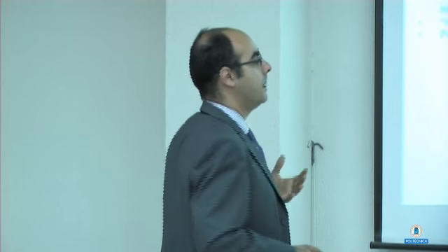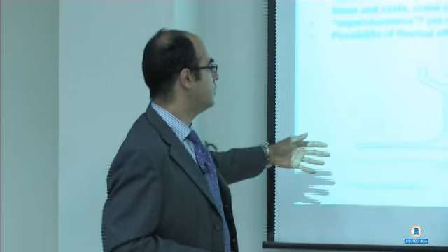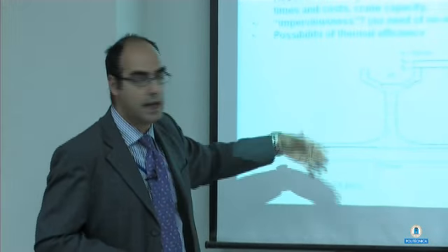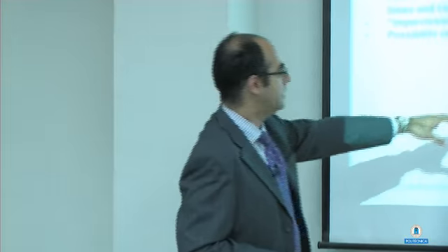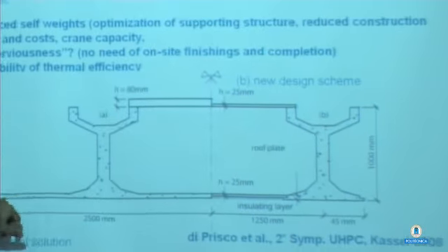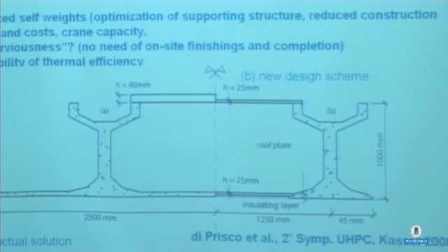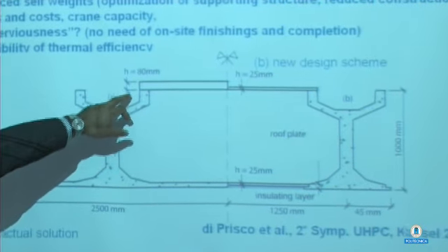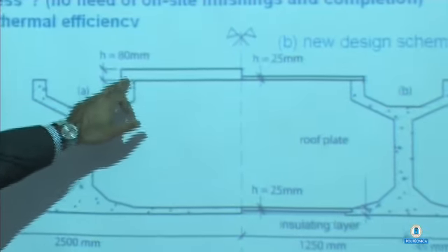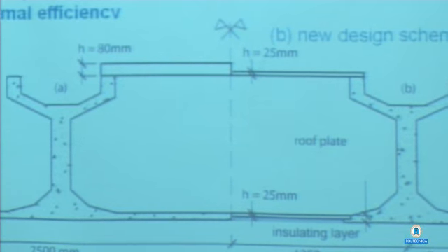So after that, we went for a structural application. Actually, this was not conventional self-consolidating steel fiber reinforced concrete, but an ultra high or high performance fiber reinforced concrete. And the problem which was asked us to solve was this. This is another kind of roof element quite commonly manufactured by a precast factory. This has an inverted Y shape, and this one is because the company wants to have the flat ceiling in the factory. And they complete it with these slabs which span about 2 meters, 2.5 meters.